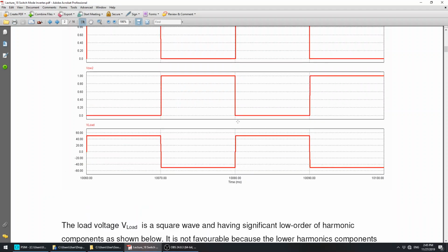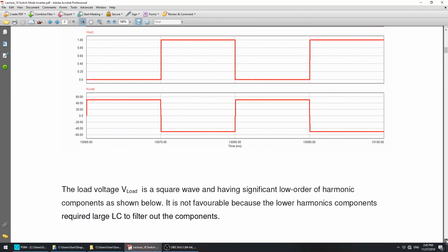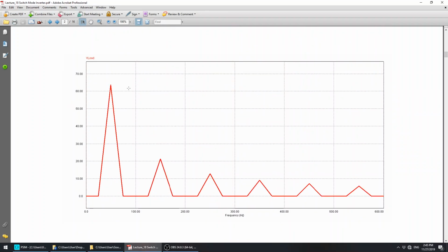When we look into the harmonics of the output voltage, you will get the familiar waveform as we did for the half wave with square wave input current. You're going to get Cn equals 4 IDC over n pi for the amplitude of the components here, right? And the harmonics are located at the fundamental and all odd harmonics for the square waveform.